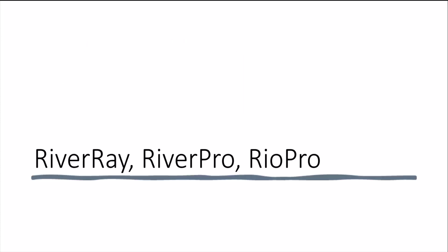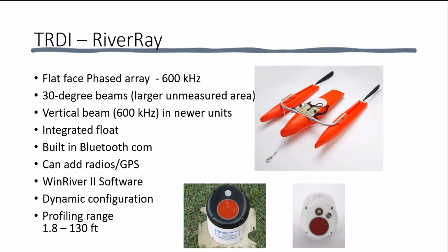The RiverRay, RiverPro, and Rio Pro are TRDI's auto-adaptive or smart ADCPs. The RiverRay is a flat-faced, phased array 600 kHz ADCP. The 4 beams are generated from the single phased array transducer and emit from the ADCP at a 30-degree beam angle. This results in a larger unmeasured area, particularly near the bottom. The newer units also contain a 600 kHz vertical beam. The RiverRay comes with an integrated float. It has built-in Bluetooth communications.